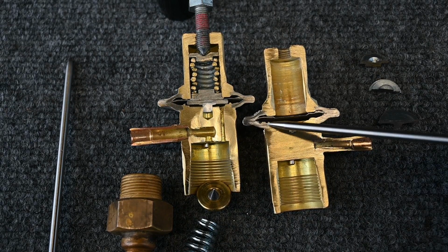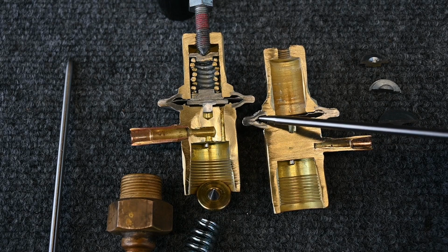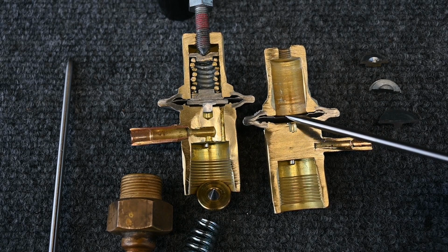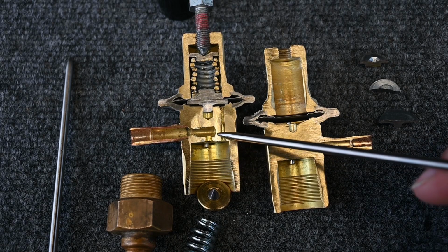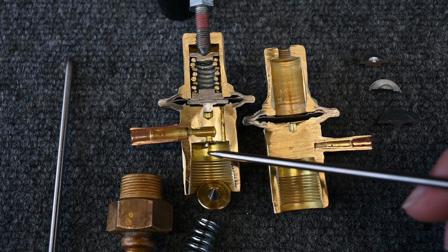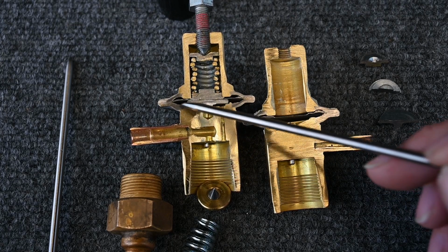Now that we took that bottom piece out, right here is a very thin piece of metal. Notice how it has this disc, very similar to a TXV. Well, this disc is a type of diaphragm. And what it does is allow this thin piece of metal to move back and forth. Remember this channel we talked about earlier? Well, this channel allows my suction pressure to travel up into this space and fill up this gap.